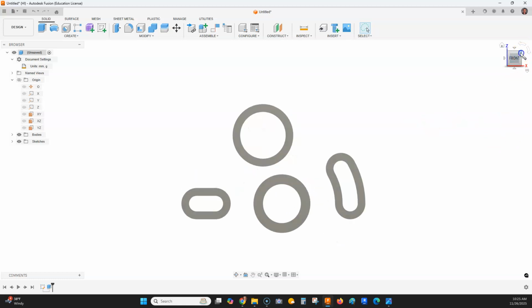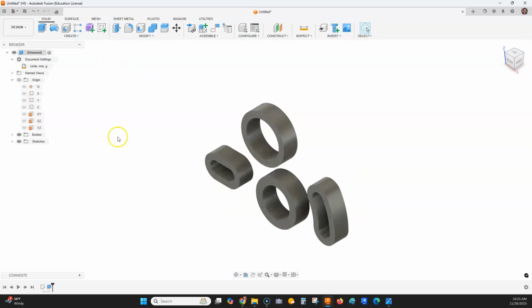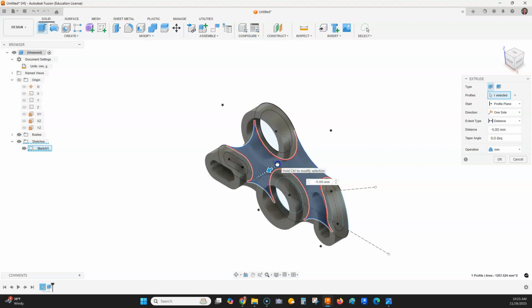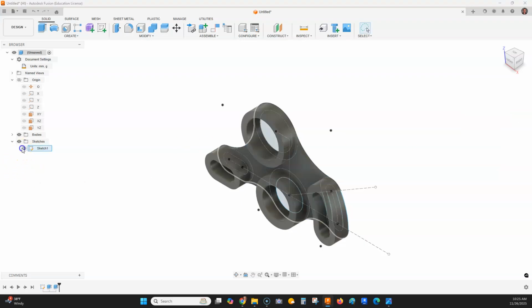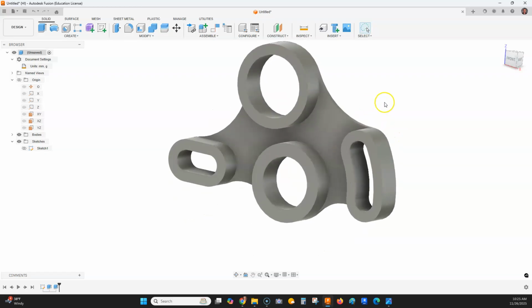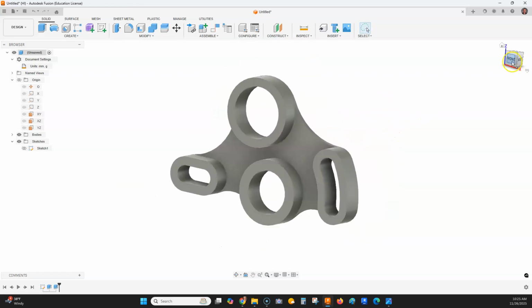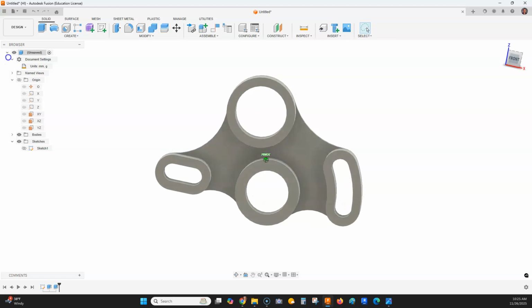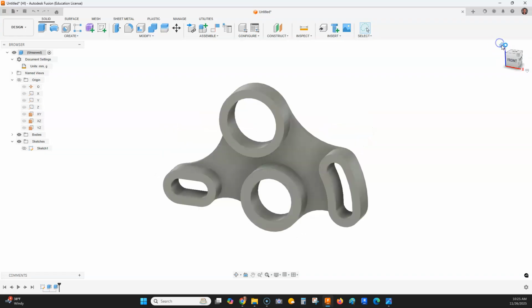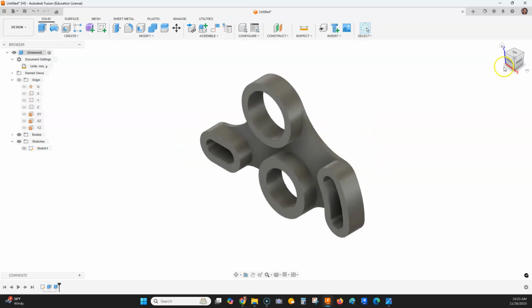See that? Now, if I want to turn back on the sketch, because you're like, man, where did the sketch go? Let's go over to sketches and let's turn back on the sketch. And I can see my other geometry here. I'm going to grab a hold of extrude, and that middle part, let's say that was meant to come out a distance of, I'm going to go -2 on this and just say okay. Let's turn off the visibility of the sketch. Now I can come in and rotate this. And a lot of times when I think of complex geometry like this, I think of gaskets for cars. This could be a complex shape for an auto part or something like that. But this is what maybe something like this could be used for.